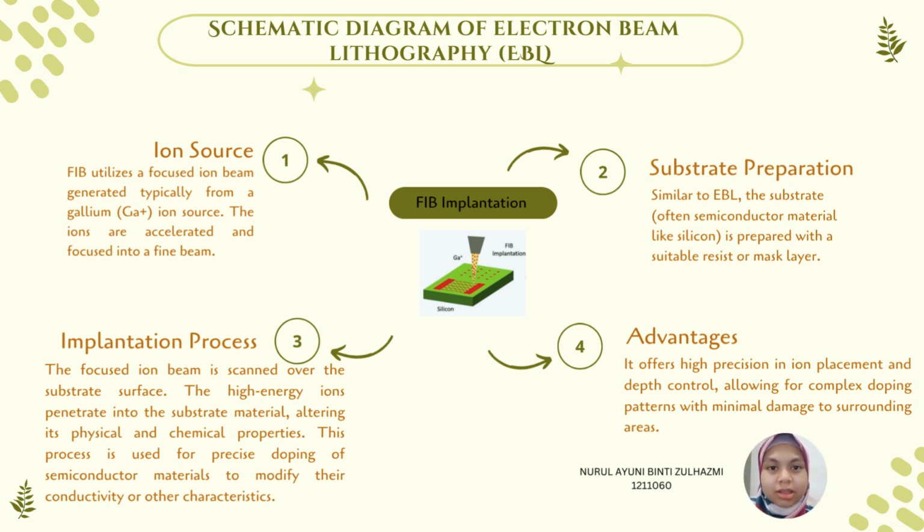Second, substrate preparation. Similar to EBL, the substrate, often a semiconductor material like silicon, is prepared with a suitable resist or mask layer. Third, the implantation process. The focused ion beam is scanned over the substrate surface. The higher energy ions penetrate into the substrate material, altering its physical and chemical properties.